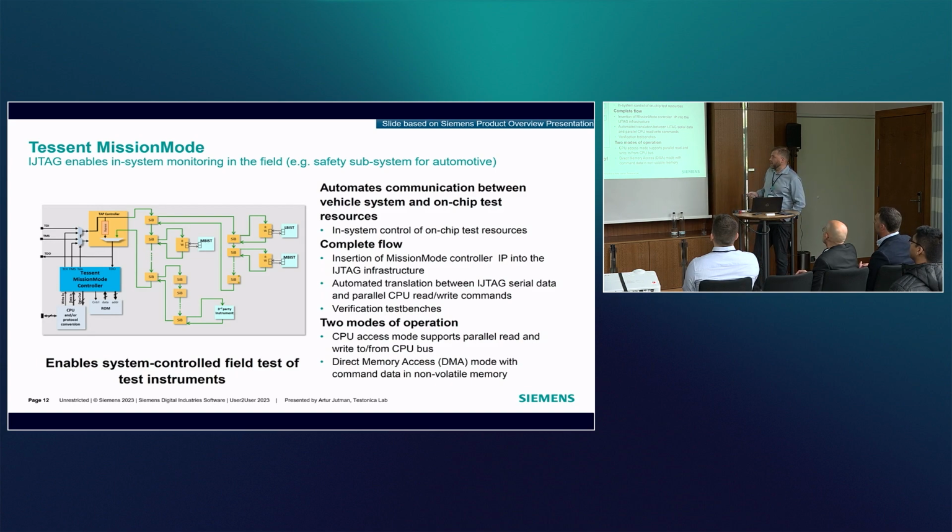Mission mode enables the embedded system or embedded software to take control over reconfigurable scan networks, IJTAG networks, to do real-time monitoring of different parameters on the chip while the chip is running in the field. So it's like doing some measurement in operation.